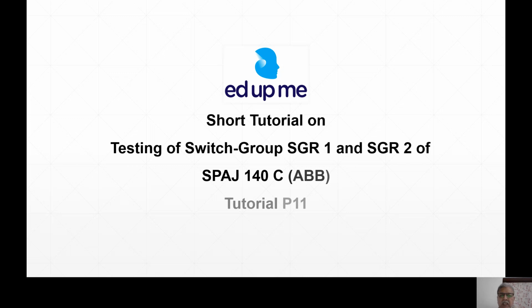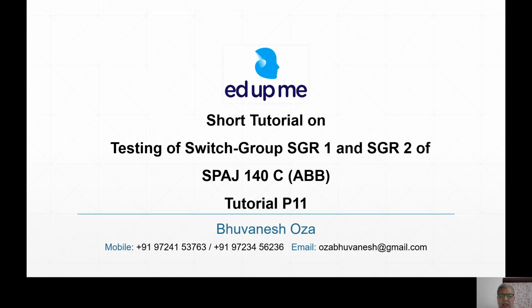We are once again meeting for yet another SPECOM version relay, SPAJ 140C of ABB make, because we want to discuss different facilities provided in the relay. The facilities provided are in the different switch groups. The first switch group was switch group function, in which there were two, SGF1 and SGF2, in which there were different characteristics of relays which can be built up, and in another group SGF2 you can